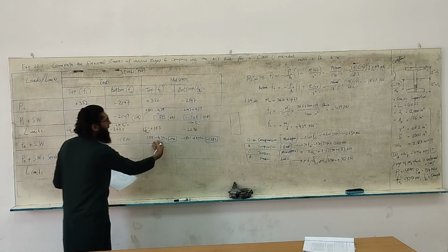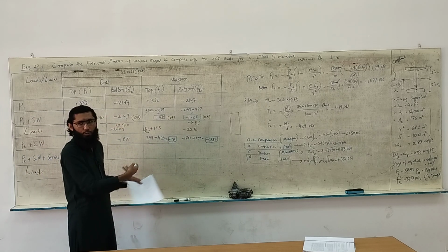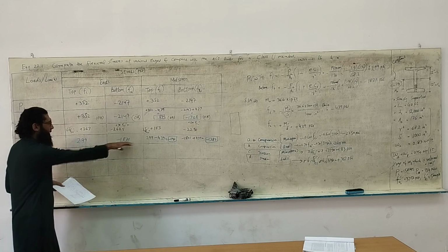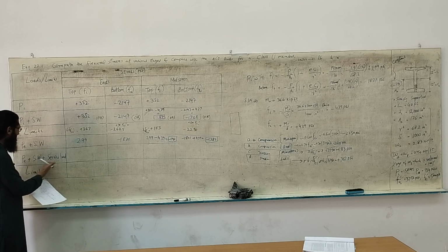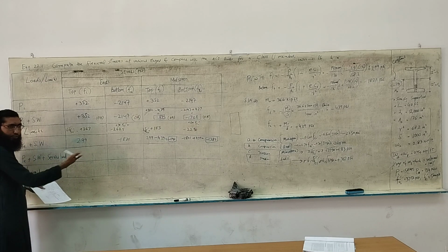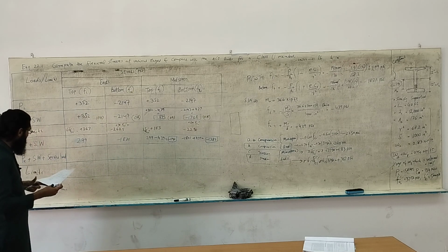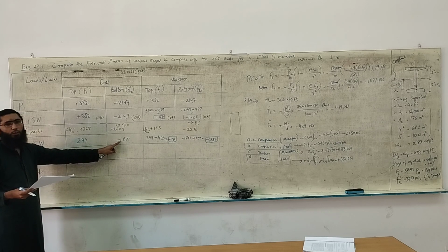So there are no limits even on this one too, but this is just something we'll use for the next step. Just for superposition, we're preparing these calculations. Okay, there are no limits for this case. This is just a calculation step. Okay, so the limits will be applied to this stage. There also we will apply limits. So let's do the math for the remaining part. Now due to pre-stressing here we have 299 and minus 1821 psi.